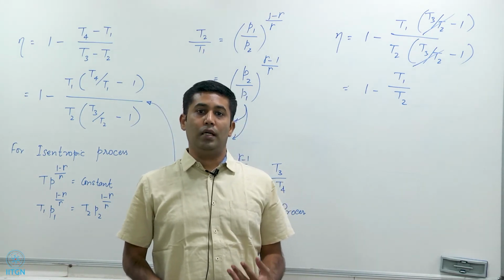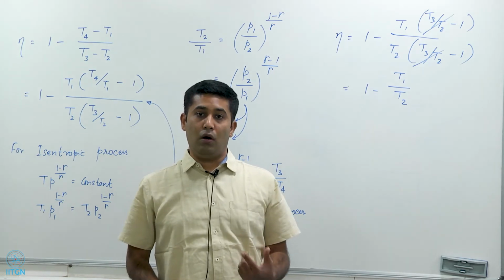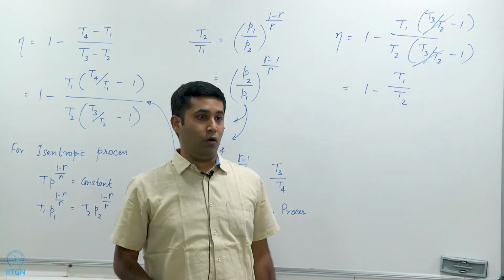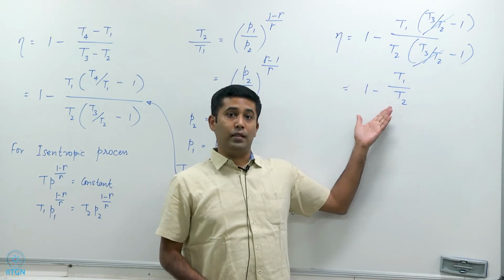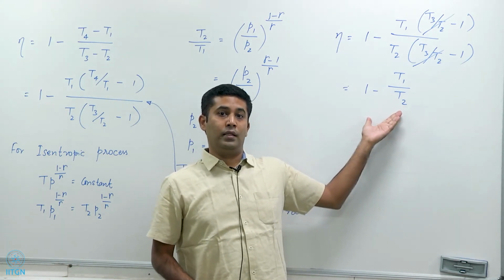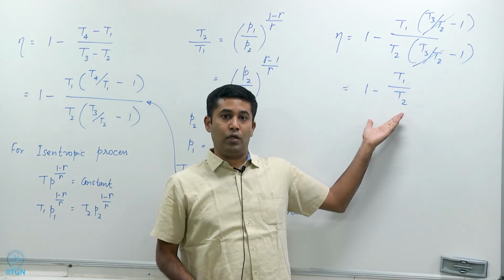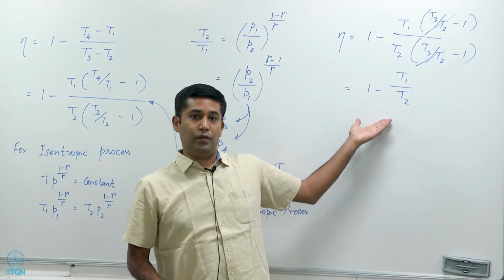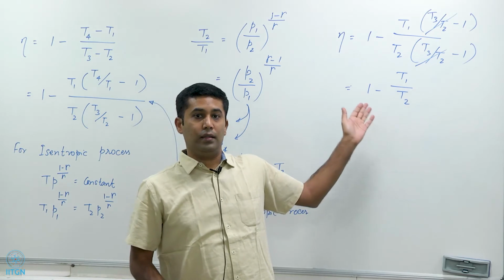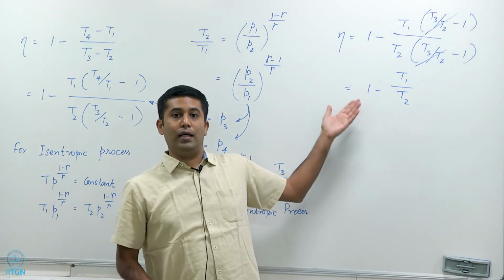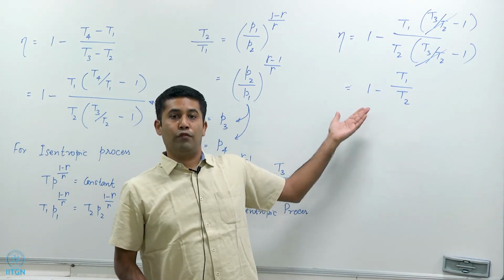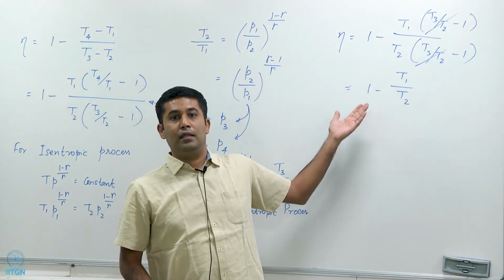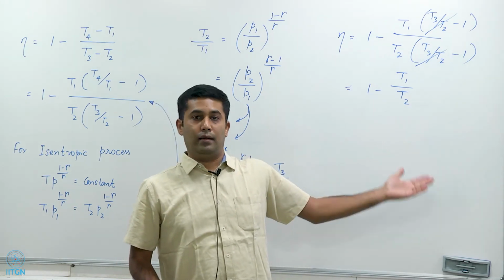So, therefore, there is no one temperature of heat addition or heat rejection, and also this is only valid when the cold air standard assumptions are valid and not otherwise. And so, therefore, it is important to recognize that this is not the efficiency of a reversible Carnot cycle, rather this is the expression for a simplified Brayton cycle that follows an idealized cold air standard cycle, right.